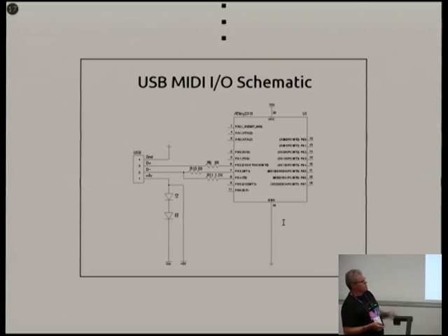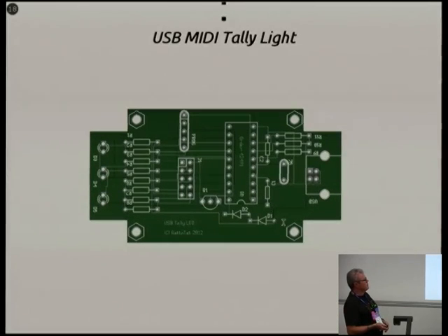You've got 3 GPIO pins on your microcontroller. That's all you need to dedicate to it. At a very low level, I think you can run it at about 6 megahertz. So it's low power, low speed, and you can run a USB 1 type device off it and do everything in software. Even for the 5 volt, you just use a couple of diodes to get it down to 3. So really basic, and then everything's a software solution from there on.